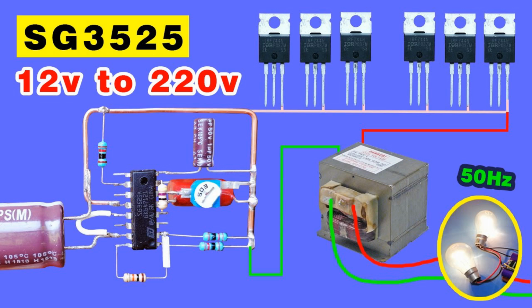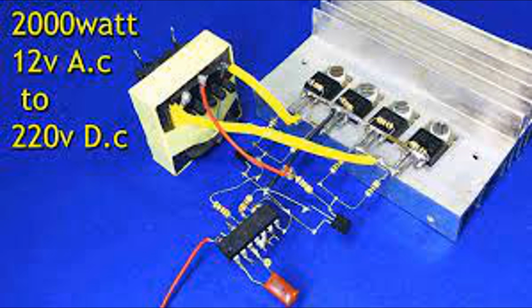Voltage-controlled amplifiers, VCAs. MOSFETs control the gain of an amplifier based on an input control voltage, used in applications such as audio signal processing, where dynamic range control is essential. Sample and hold circuits: MOSFETs are used to sample an analog signal and hold its value for a period, which is critical in analog-to-digital conversion and various signal processing tasks.